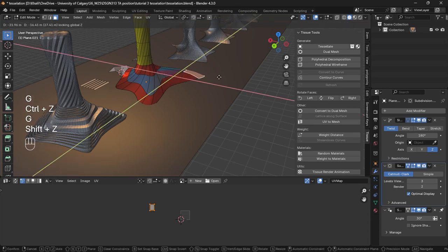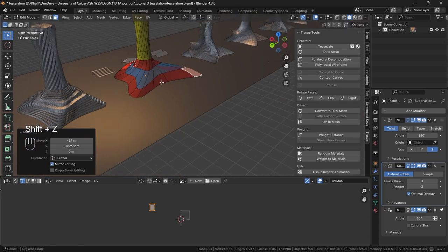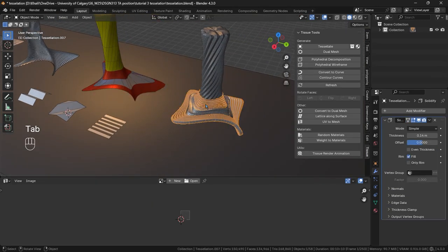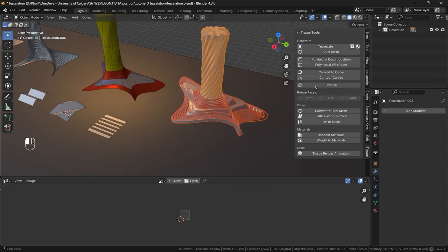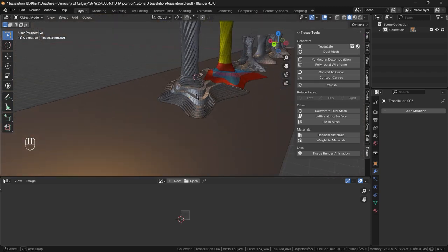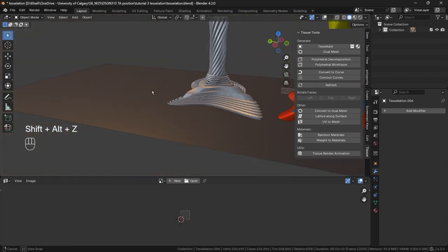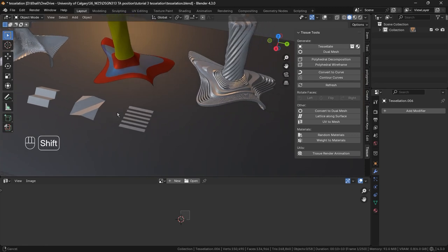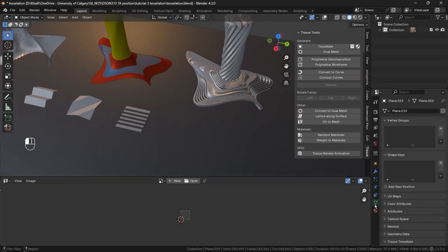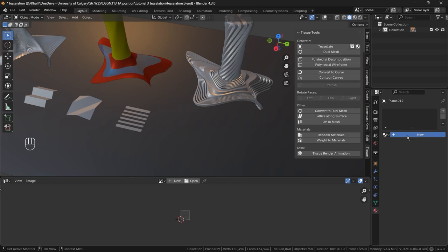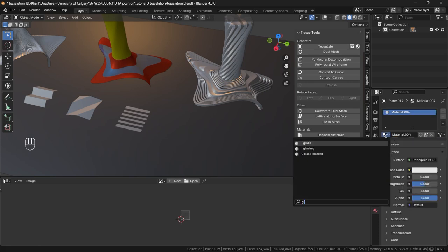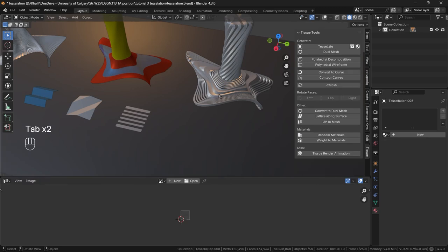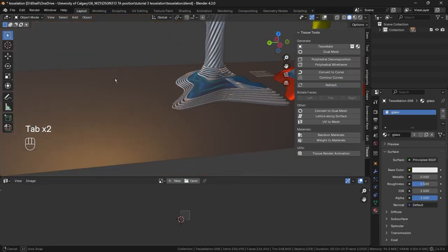J, move the face here, and then tab out, and I will select these tessellation, refresh, everything will change accordingly to the original change. And if I change the material of these patterns, for instance, this pattern here, I make it glass, and I choose the glass material previously made, and I will refresh this, it will become glazed.